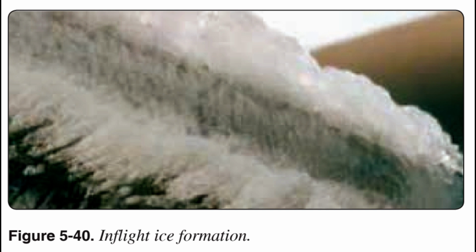As little as 0.8 mm of ice on the upper wing surface increases drag and reduces aircraft lift by 25%. Pilots can encounter icing in any season, anywhere in the country, at altitudes of up to 18,000 feet and sometimes higher. Small aircraft, including commuter planes, are most vulnerable because they fly at lower altitudes where ice is more prevalent. They also lack mechanisms common on jet aircraft that prevent ice buildup by heating the front edges of wings. Icing can occur in clouds anytime the temperature drops below freezing and supercooled droplets build up on an aircraft and freeze. Supercooled droplets are still liquid even though the temperature is below 32 degrees Fahrenheit, F, or 0 degrees Celsius, C.